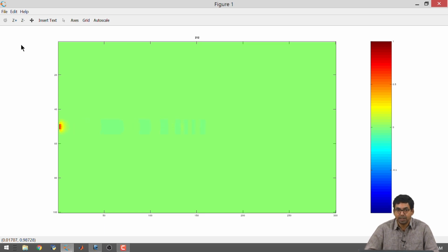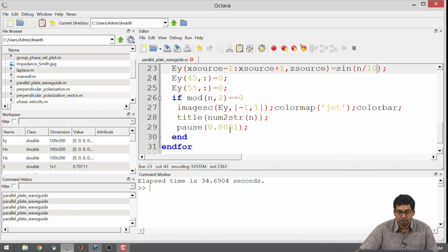So, the way to visualize cutoff frequency should be clear. Even if you are not aware of the formula, you can take the code, sweep the frequencies of the source and get a decent estimate of what your cutoff is going to be.